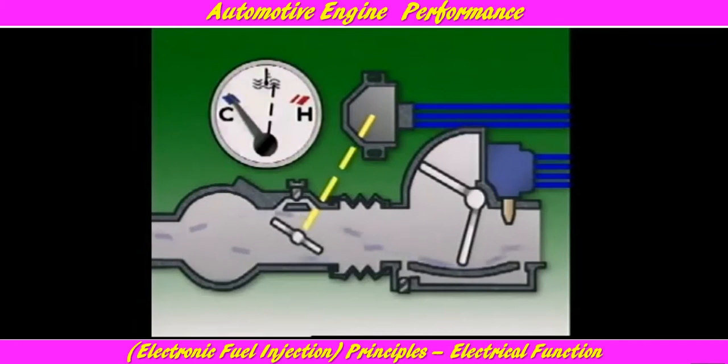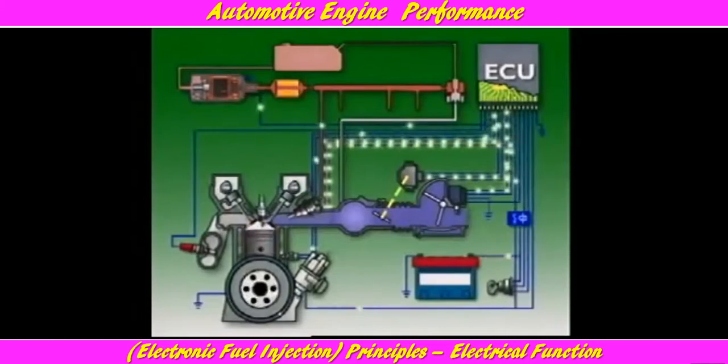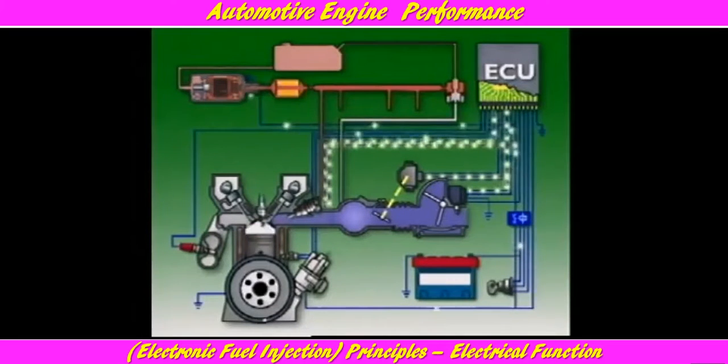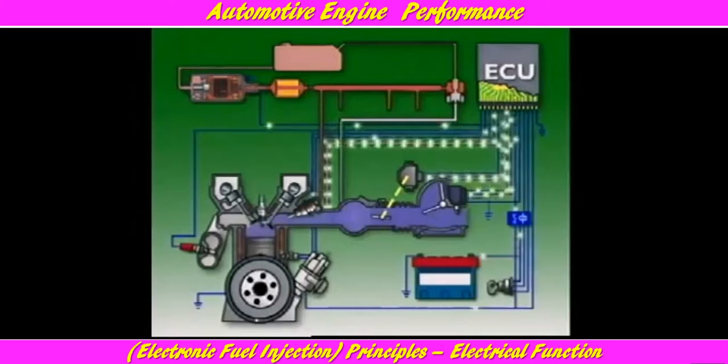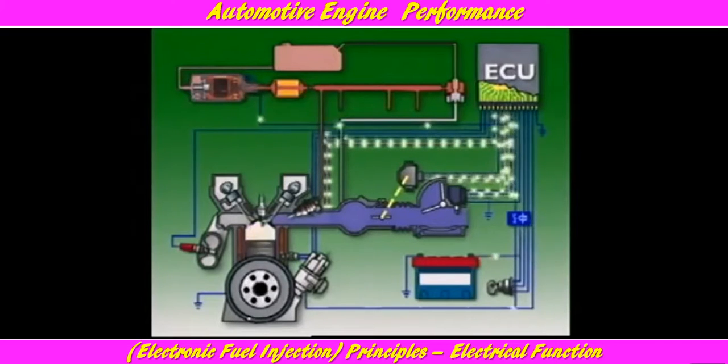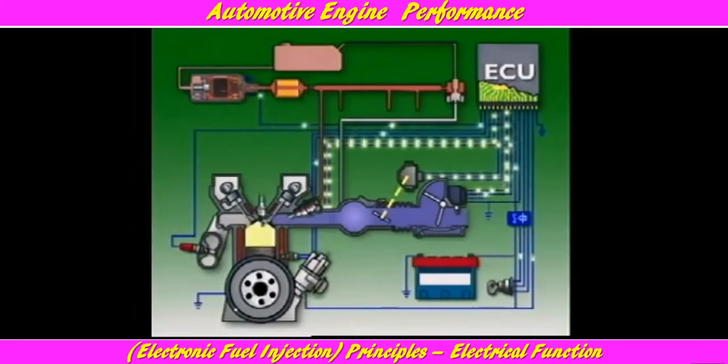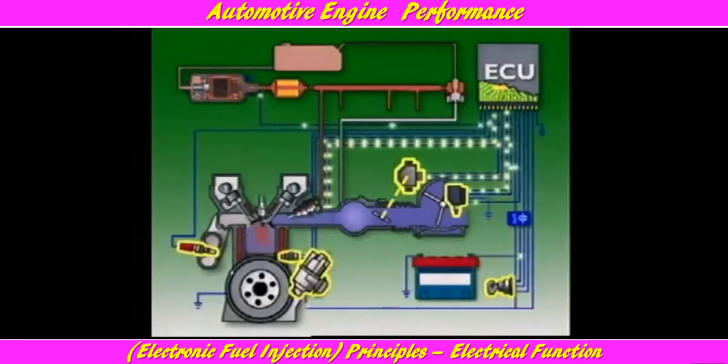Coolant temperature is still below normal. These factors combined produce a fuel setting. It is less than if the throttle were opened suddenly for acceleration or to overcome increased load. However, it is more than it would be if coolant temperature were at its normal level. The varying signals can be supplied by variable resistors, by switch contacts, by voltage pulses from the ignition system, or by sensors.